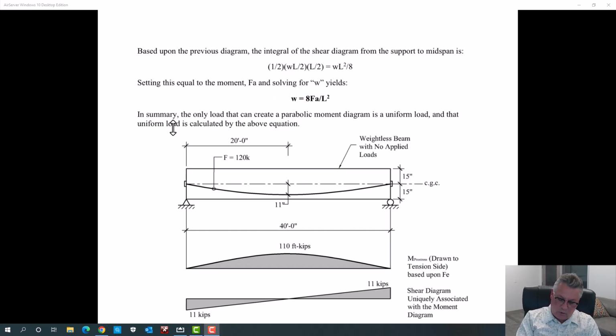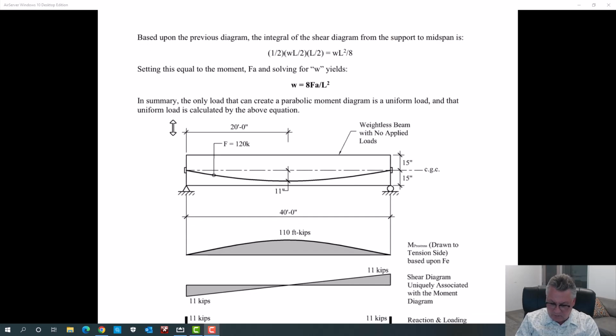This is going to be the equivalent prestressing load. So remember, we just have a tendon that's stressed inside concrete. And that primary prestress moment diagram is F times E at every location. Okay, we can use that to just go straight and calculate this moment diagram. What's going to be much more powerful for us is to calculate this fictitious equivalent load and use that load as a load case to come up with this same moment diagram, this same